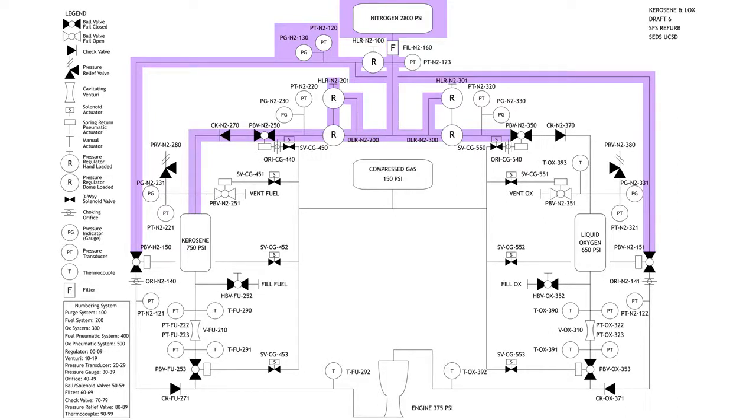So you're saying that this valve here gets open? Yeah. Say for example, all our propellants are filled, and I opened my nitrogen bottle. Right now, my regulators are regulating at the lowest they can possibly go, probably 5 psi. And now I'm going to open my pneumatic ball valve N2 250 from the bunker. So it's going to be receiving a really low pressure, and it's just going to be open while you're changing the regulator to higher and higher pressure.